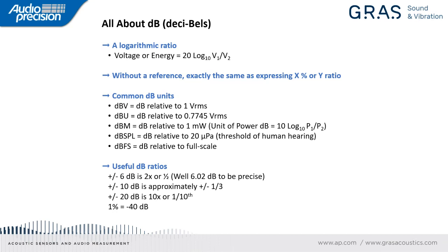And then dBFS is dB relative to digital full scale. So 0 dBFS is the maximum RMS signal that a sine wave can represent in a digital sampling system.